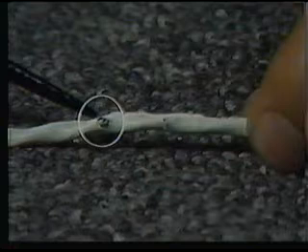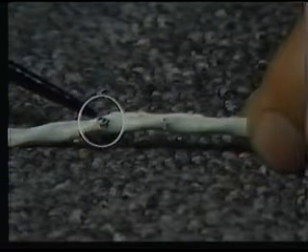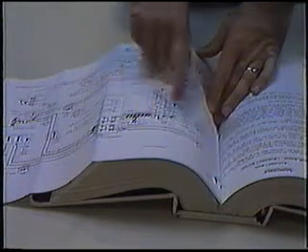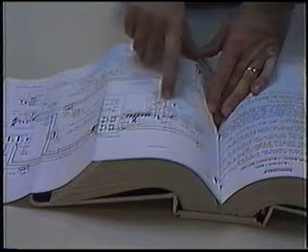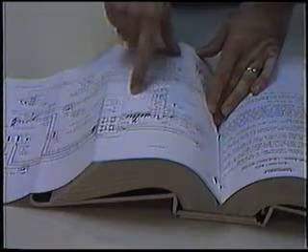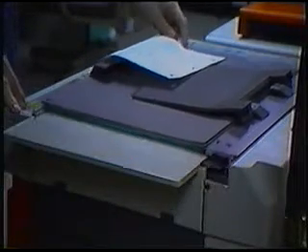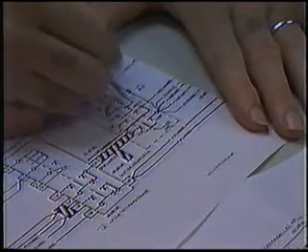Suspected wire segments should be replaced using correct and safe routing. As in any troubleshooting of theory-related systems, use logic and common sense in attacking the problems. Look at the wiring diagram and isolate the fault signal portion of the circuit. If a copy machine is available, copy the relevant portion of the wiring diagram and use colored pencils or similar marking devices to highlight the segments in question.